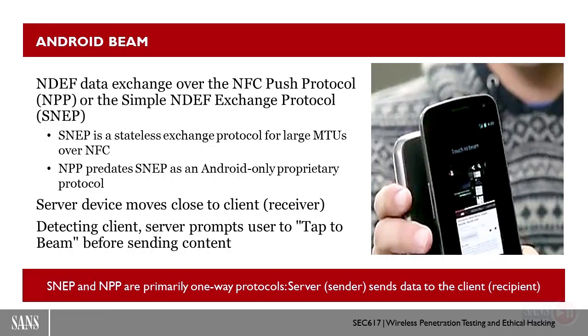Some other ones use the NFC push protocol, or simple NDEF exchange protocol, NPP or SNEP, for transferring large amounts of data, specifically changing those PICC and PCD roles for doing data transfer of, say, music or contact information, using NDEF-style records over NFC.